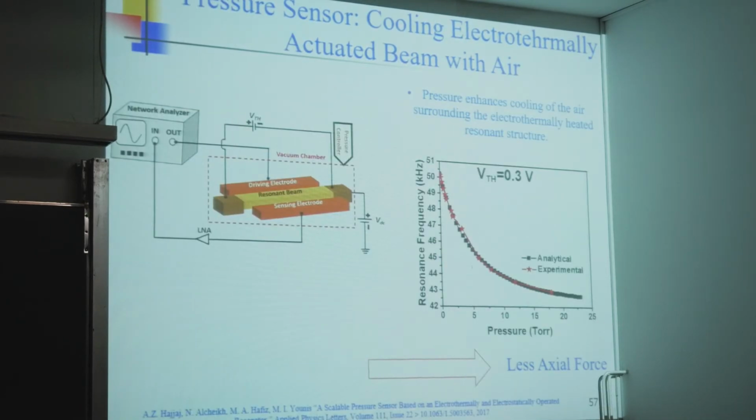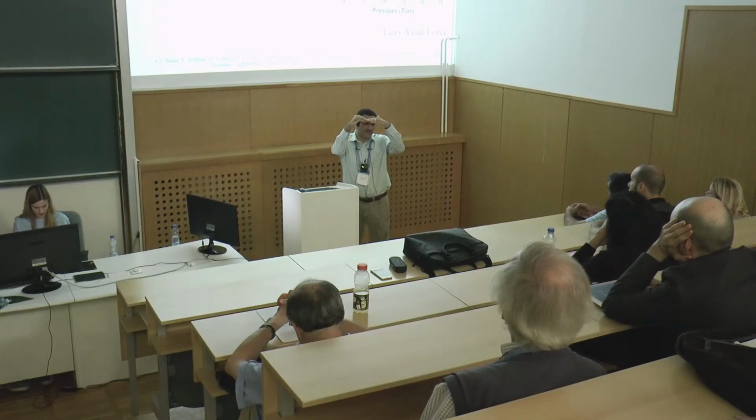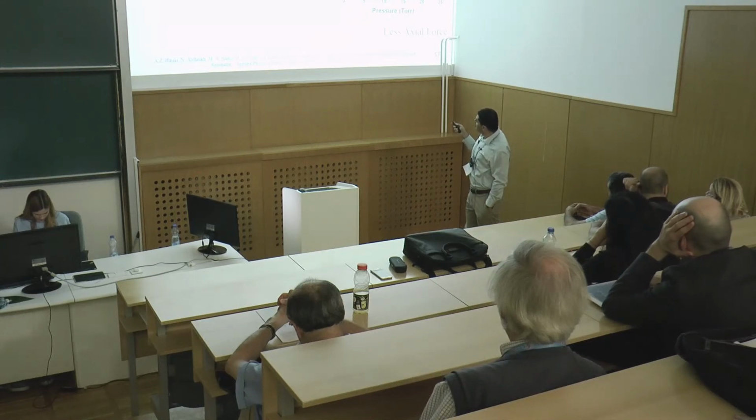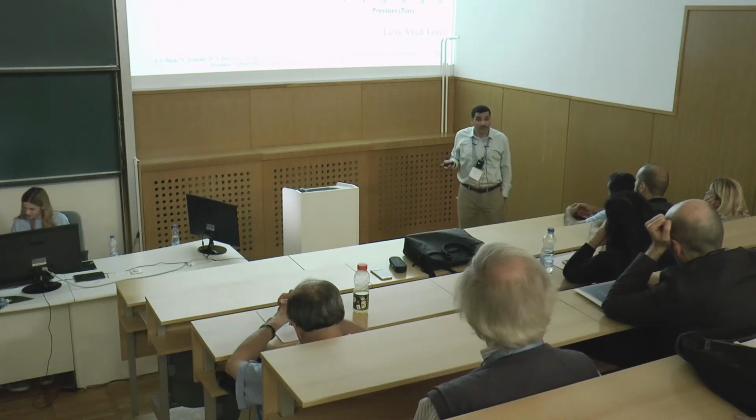All right, so I'm going to keep throwing applications at you until my time is up, so bear with me. Another linear principle, but I will twist it nonlinearly in a minute: if you have this wire and you are heating it, then you can cool it. And when you cool it, if it's an arch, cooling means change in the resonance frequency, less curvature, right? So I literally can have a pressure sensor where measuring the resonance frequency will be an indication for the amount of pressure I am having.